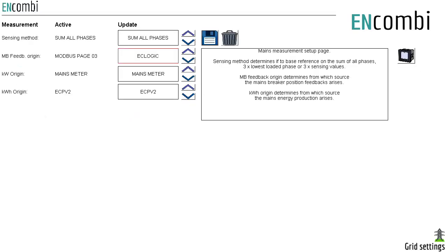EC logic is the next option. This option will be used in complicated electrical infrastructures where the utility cannot be counted from the common AC busbar as the utility is not connected to the same PV busbar. In such installations, the utility condition can be customized within EC logic.